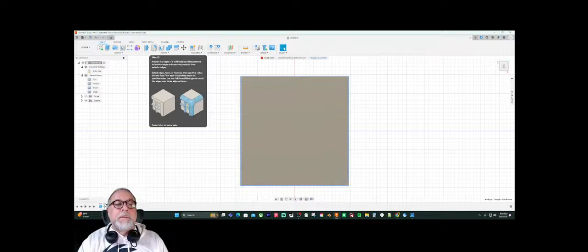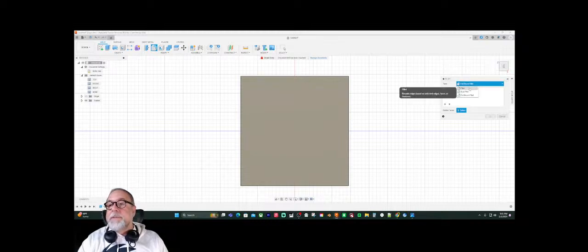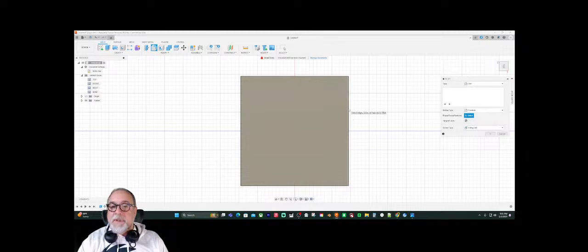I'm going to come up here and do a fillet or a rounding or a scroll. You can change how you want it. It can be a full round. It can be half round. It can be a fillet, whatever it happens to be. And I just unselected all my edges, so I'm going to select all those again. One second. So you can see how easy it is. Now all 4 of them are selected. And now, again, I can type the numbers in here that I want.